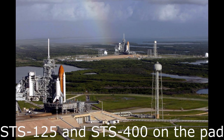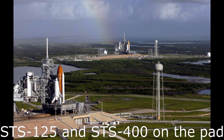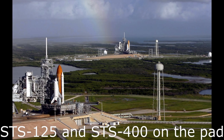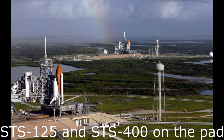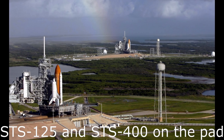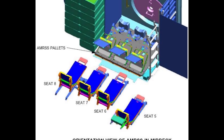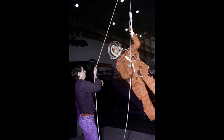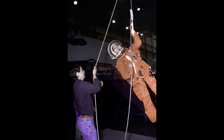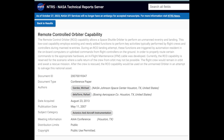One might be wondering why such a mission wasn't initiated when Space Shuttle Columbia was in orbit for STS-107 with a hole in her wing, and the answer is simple. These contingency missions were planned after the loss of Columbia. The rescue missions had several pieces of specific hardware to be flown, including extra seats, extra handholds, mounting provisions for the cooling units of extra spacesuits, mounting provisions for a cable that could be used to transfer crew, in addition to a remote control orbiter cable that could be used to deorbit the damaged shuttle without a crew aboard.